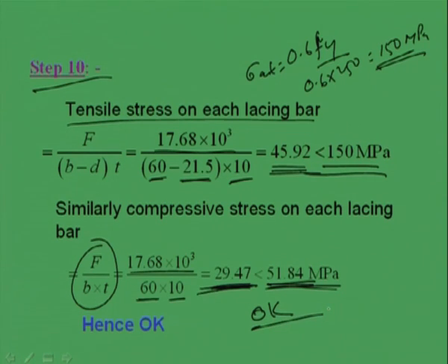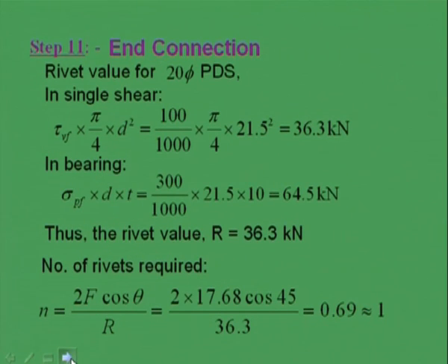All points of view means from compressive point of view, from tensile point of view, from buckling point of view. Okay. So, we have checked as per the clause. Next what we will do? Next is the last step, that is end connection, design of end connection between lacing and the main frame, right.